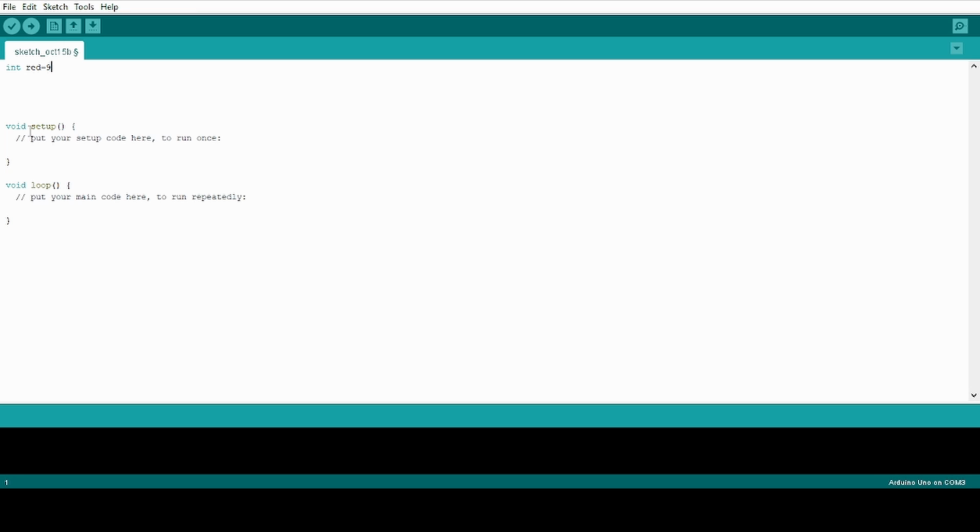So when you're doing your project, make sure you're using one of the pins on your Arduino that has a little curve mark on it. Most of those numbers are 3, 5, 6, 9, 10, 11. All of these have a little squiggly, and if you're using analogWrite, you can only use this command with those specific pins. Some of the other commands you can use with any pin.